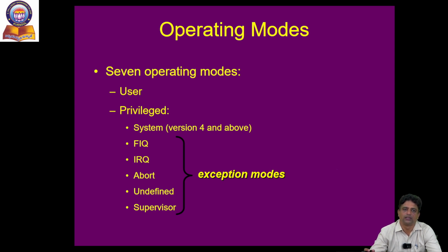When a controller or processor leaves its current position and operates on an interrupt request, it is treated as interrupt service routine mode. If it is working specifically on masked interrupts, it is one state. If it is working on non-maskable interrupts, it is another state. Such states are now given headings and are the privileged mode names under the ARM architecture.